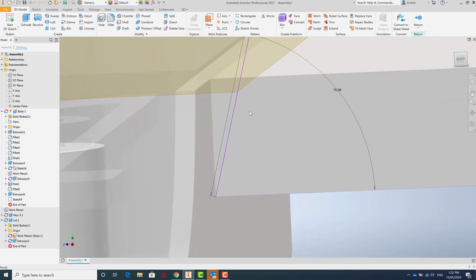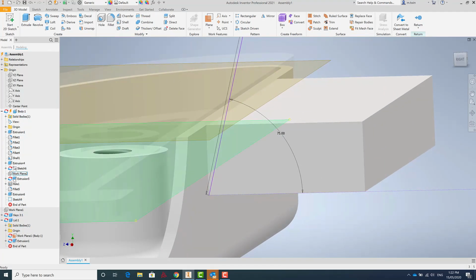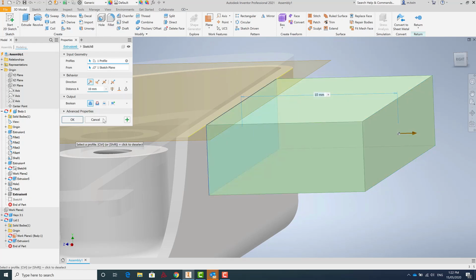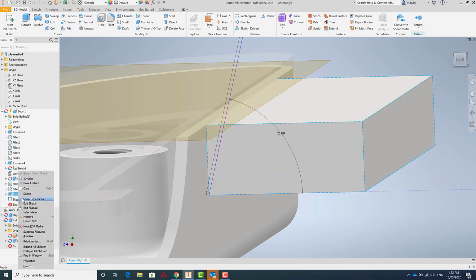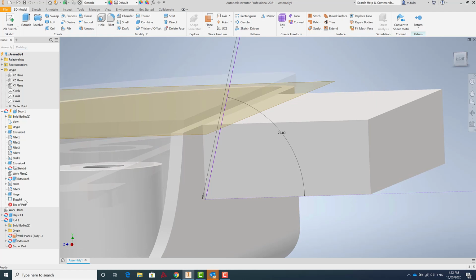So I finished that sketch a little bit early. I've got to get back in there and turn that into a cut profile. So into our body, this is where naming things gets really useful. So I'm going to start naming stuff. We'll call this one the hinge. So I'm going to rename, there should be a tool there. Oh dear. It's one of those things they've changed in 2021. Here we go, we'll call this hinge. And sketch one we'll call cut profile.